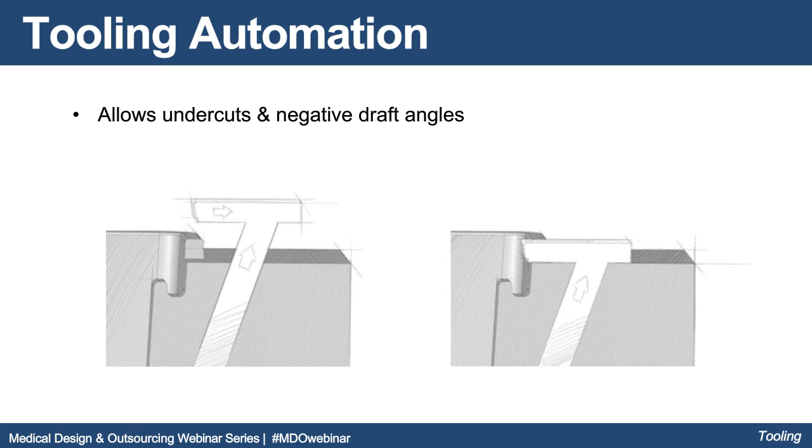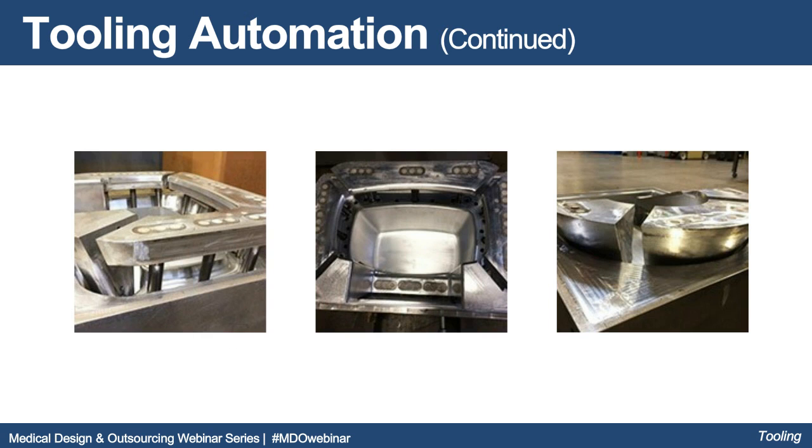Basically, we're building a cavity of an injection mold that can include actuating slides. The pictures below show various molds and actuation being automated. So we're basically lifting undercut sections of molds to show how we would move a section and allow the molded part to come out of the tool surface.